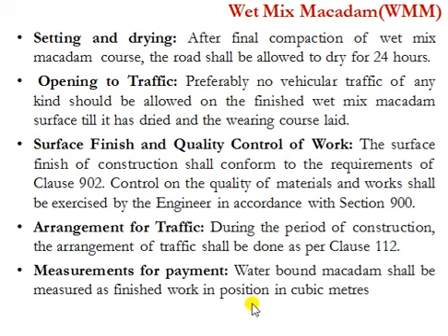So the final stage or final process is measurements for pavement. Waterbound macadam shall be measured as finished work in position in cubic meter. So the waterbound macadam is measured in terms of cubic meter.